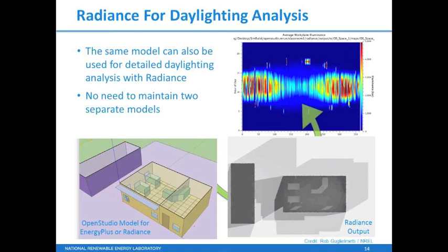Typically in an energy model, your thermal zones dictate the boundaries of the spaces, but those don't necessarily correlate to actual physical geometry. So we've allowed an object called an air wall, which is a thermal zone boundary that doesn't actually have an architectural counterpart to it. In other words, it's an energy modeling construct, but it doesn't represent an actual wall or physical geometry in any way.